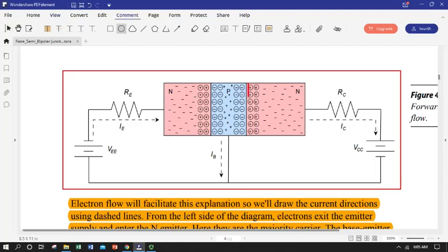They get across the interface, and they're going to see effectively a zone depleted in the charge that they're carrying, this net positive charge. So this portion of the collector really wanted to have some electrons, and it doesn't because it recombined with some of those intrinsic holes in the base. It's perfectly happy to get some electrons coming scooting across the base.